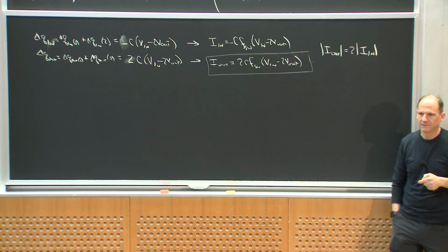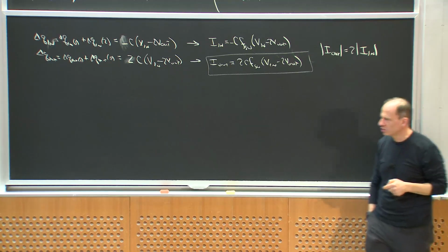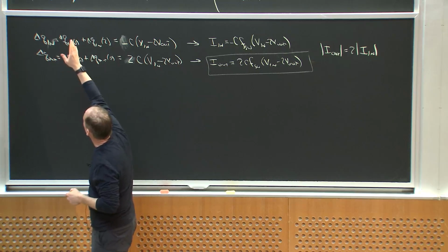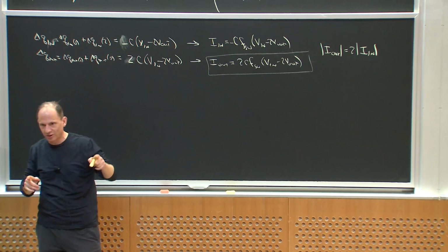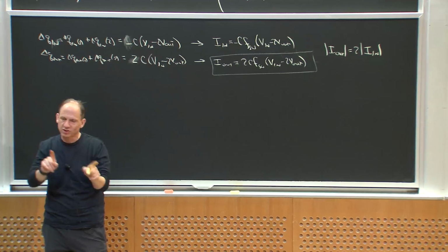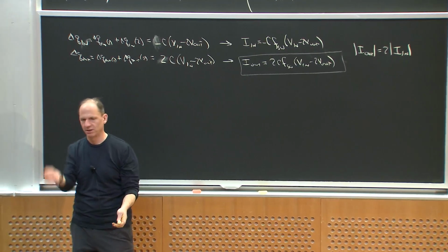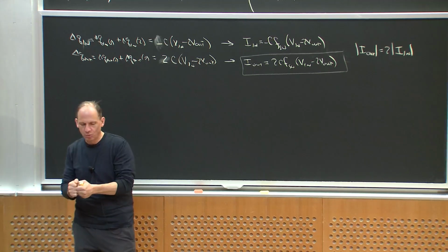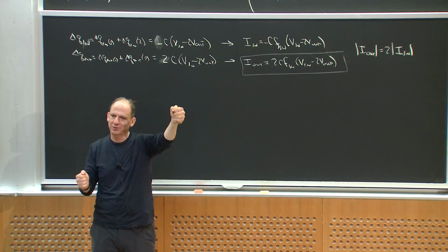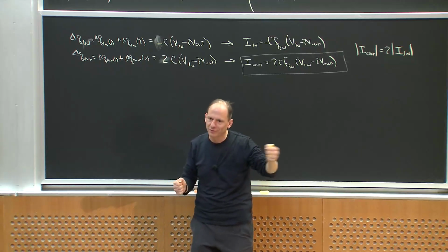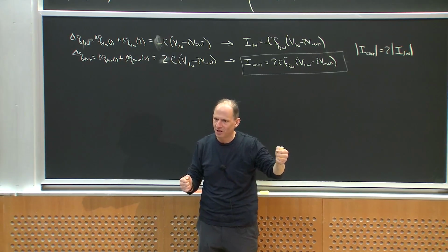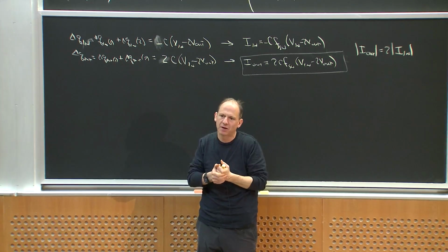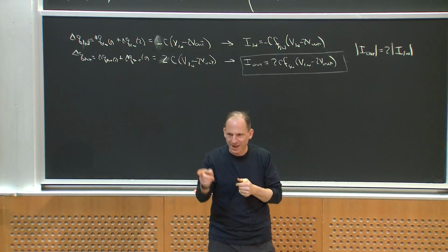Is this assuming a 50% duty cycle? That's a good question. So long as the intervals are such that I fully charge and fully discharge in each subinterval in state 1 and state 2, the actual duty ratio doesn't matter in this mode of operation. The only thing I've assumed is that I'm waiting long enough in state 1 for the capacitor to get to its final voltage, and long enough in state 2 for the capacitor to get to its final voltage. As long as I've waited long enough in both states, their actual fraction of on times doesn't matter. We'll come back to that shortly.